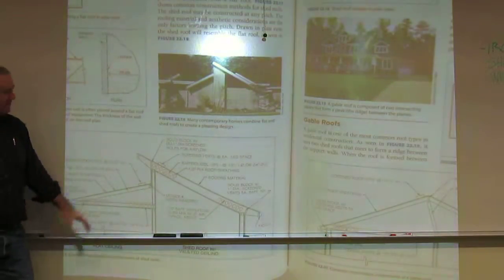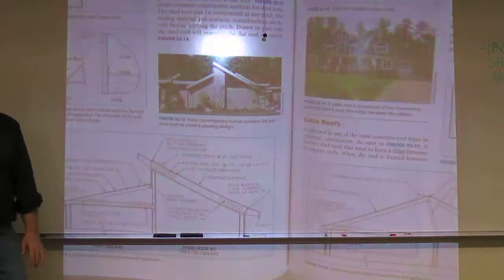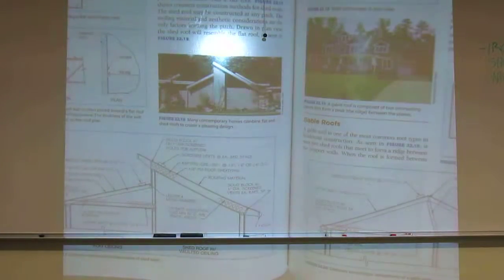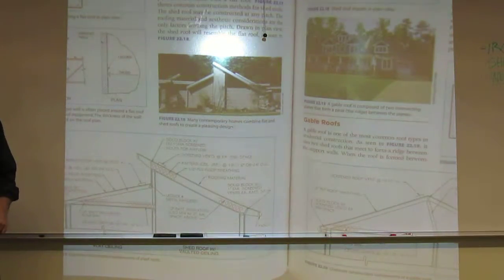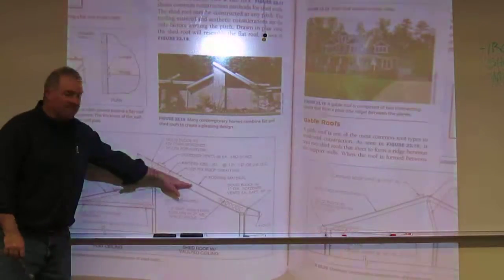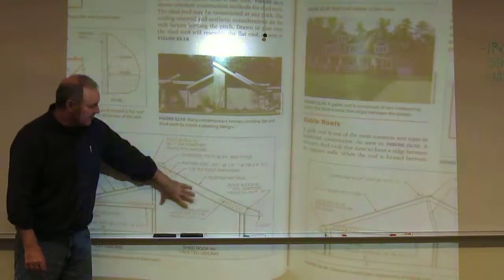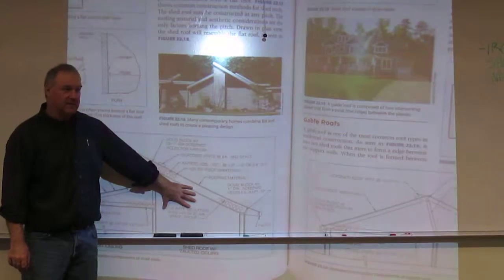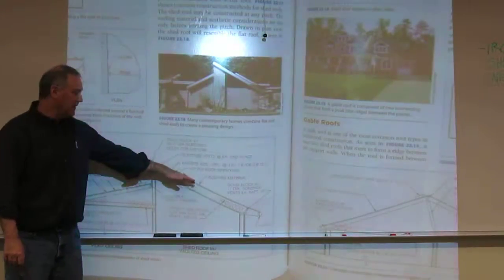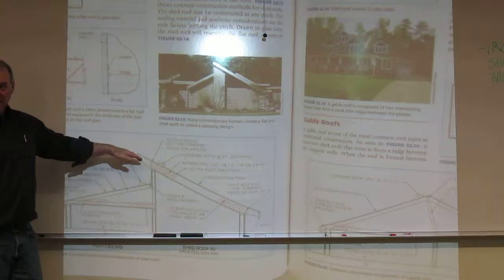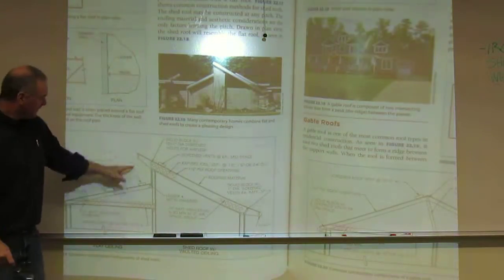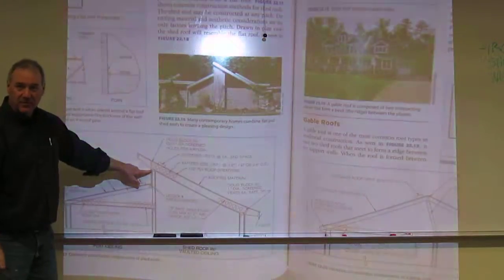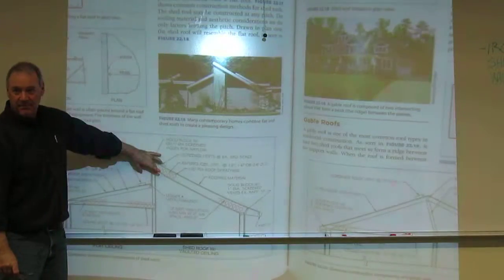Now a shed roof, we have some different components. These are done with trusses. A lot of times they're done instead with a rafter system. Now, rafter just means one board here. It's not a collection of boards like a truss. So it's one board. This would be a rafter, and we'll talk more about this also in structural. You might have purlins and girders. In this case, they're using a wall to support it. You could have a beam up here.